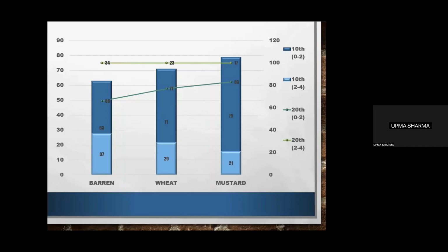So, the transition zone is showing good results because the SSD pipes which were installed in the on farm development crop area were almost in the transition zone, which is 1.2 meter below the soil depth, considered as the transition zone. So the model has shown us the results for a decrease in the salinity values.